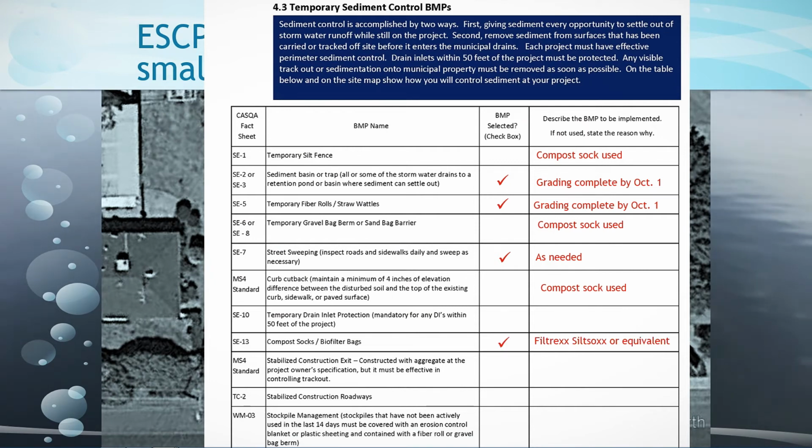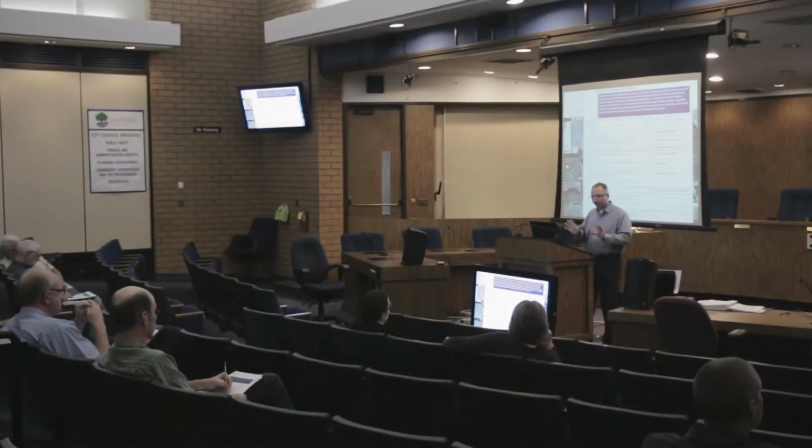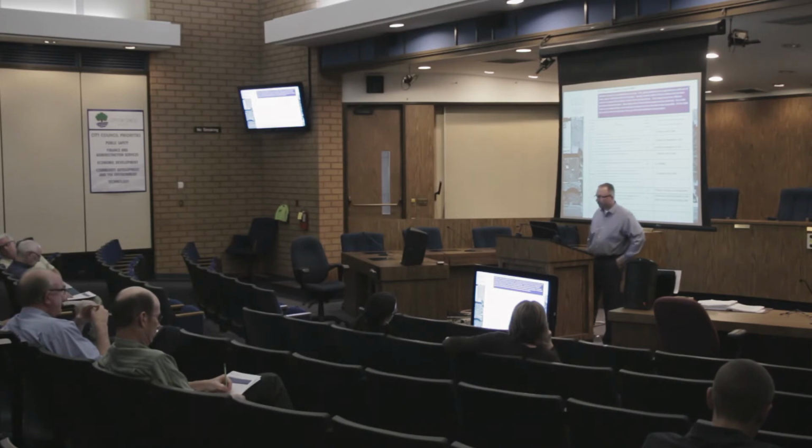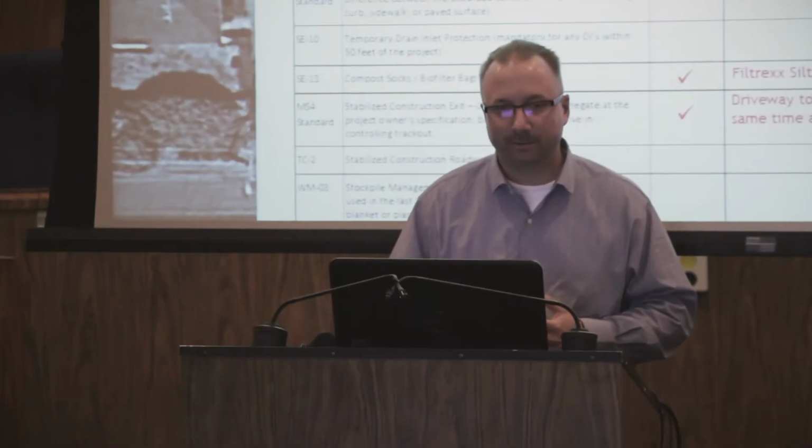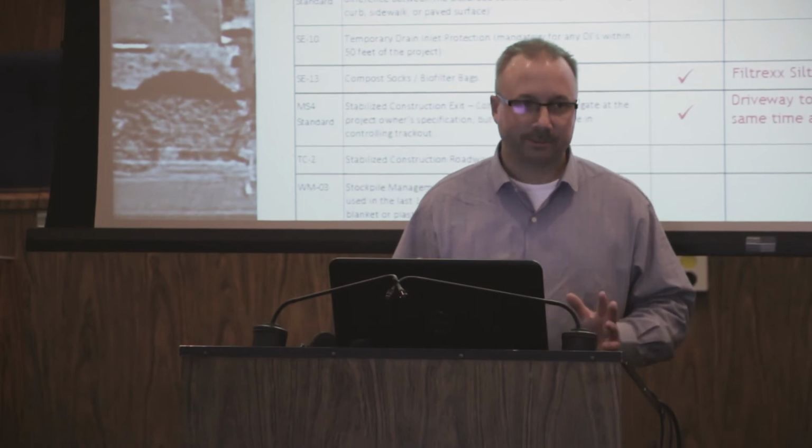I'm going to skip drain inlet protection. We'll come back to that. Compost socks, yes, and I'm going to show you why and where we're going to use it and the rationale why we're going to use those. Stabilized construction entrance, yes, but it's not what you would typically think about. It's not that TC1 as we call it many times, with that big rock and the rumble strip that knocks the mud off the tires. No, obviously a project this size doesn't need it.